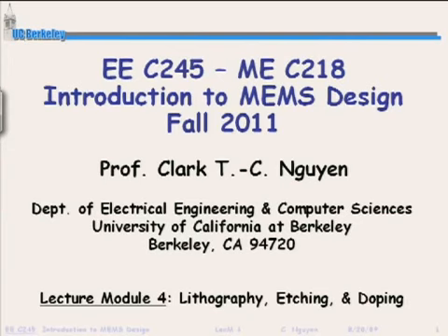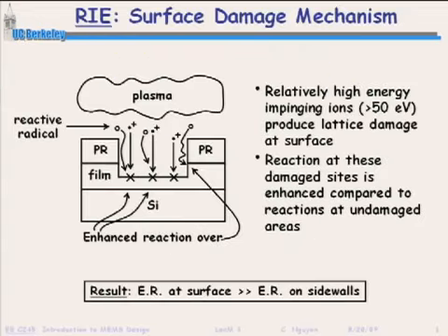In reactive ion etching, however, like we said last time, because they're neutral radicals and they cannot be directed in any particular direction, they etch equally in all directions. So your generic plasma etch is an isotropic etch. It etches sideways and vertically at exactly the same rate. Usually that's the case, and often because it's a gas, it can go in all directions without too much trouble. To make it more directional, which is what we like to have, so you'll see very soon that we like to have straight sidewalls, which you're seeing right here, which obviously you don't get with an isotropic etch.